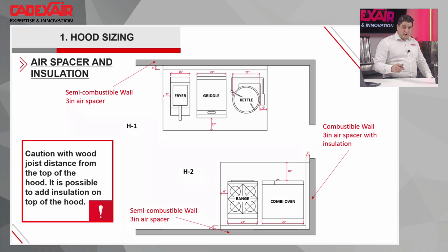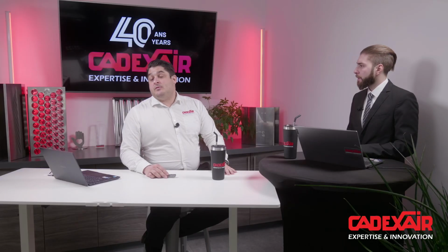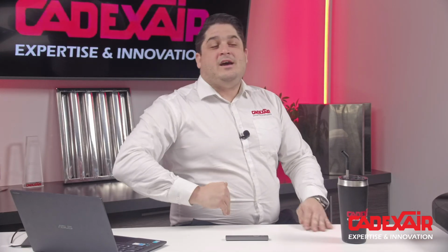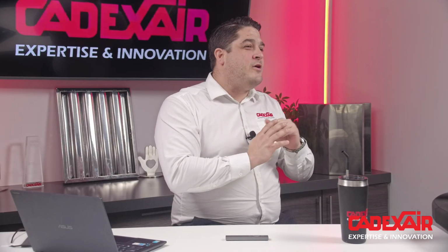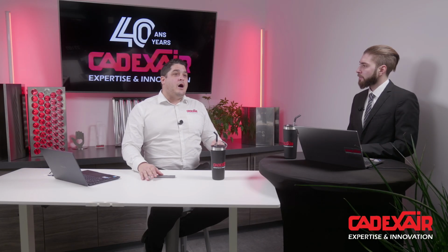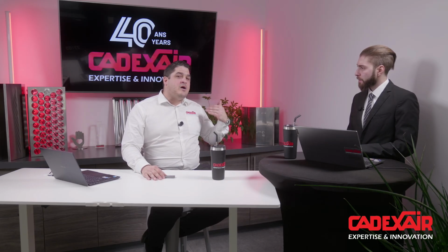Something also important: do you know what joists you have in your ceiling? Yeah, they're wooden joists. I didn't think that was important to mention. Is it something that you need to know? Yeah, it's really important because it's not only the side of the hood, it's also the top of the hood. If you remember correctly, when we talked a bit earlier about our tapered hood, you are at exactly 18 inches of clearance between the top of the hood and your joist or your finish, or the maximum space you have in your ceiling.